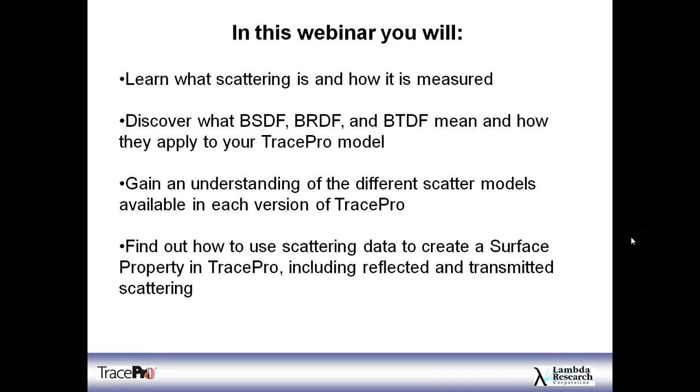In today's webinar, we're going to take a look at what scattering is and how it's measured. We're going to talk briefly about what BSDF, BRDF, and BTDF are. You see the terms mentioned quite a bit in TracePro, so what do they mean and how do they apply to your TracePro model? We'll try to give you an understanding of some of the different scatter models that are available in each version of TracePro. We'll find out how to use the scattering data that you may have, measured scattering data, to create a surface property in TracePro. And we'll look at a reflected and a transmitted scattering example for that.